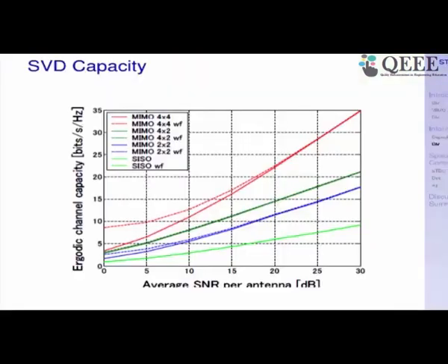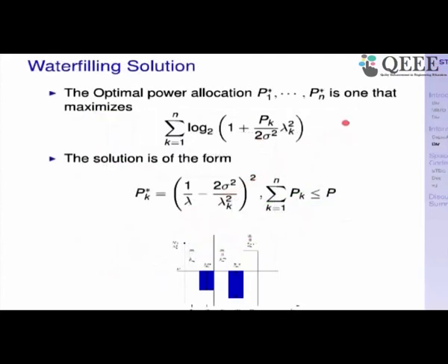Yes, anybody else? Any further questions? STCAT, go and see, I will take you to the derivation. See there. For the case when the channel is known at the transmitter, the additive noise from the channel comes into picture here, 2 sigma square. It is basically contributing to the threshold above which only putting power on this mode is going to give you advantage. Otherwise there is going to be no advantage. So you can think of this as the effective noise floor that is seen for a given eigen mode. This term is basically the noise floor. A noise density you typically take as N0, flat, wide spectrum. So you can take 2 sigma square equal to N0 if that is your confusion. Okay. Any other questions?